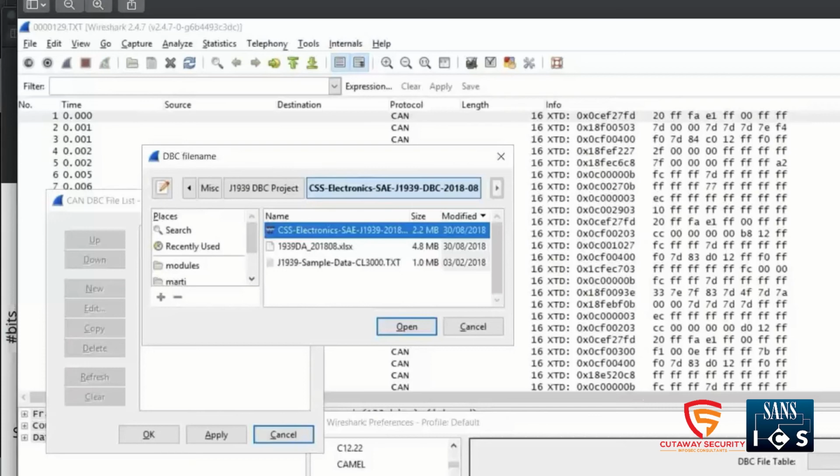It's another example of what a lot of information security professionals that aren't familiar with control networks hear about, these protocols that are insecure. They're not protected by some type of tunnel or encryption layer, and so this is an example of that. But it's also an example of something where encrypting these messages would induce some type of delay in transmission. It's going to make the messages bigger, but also the processing on the endpoints is going to be more complex as well. So this is a good example of that.